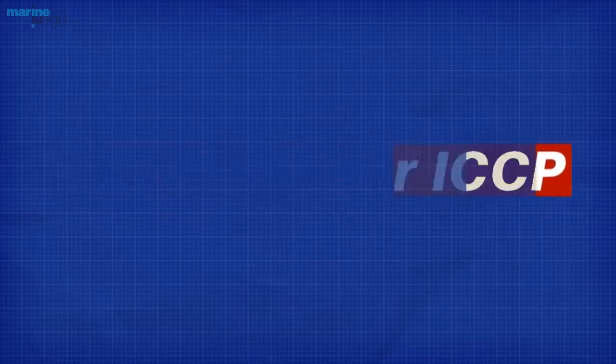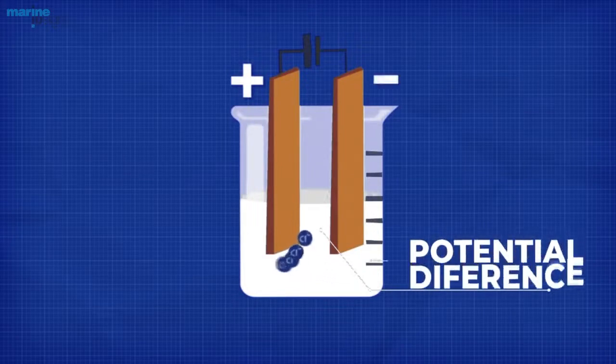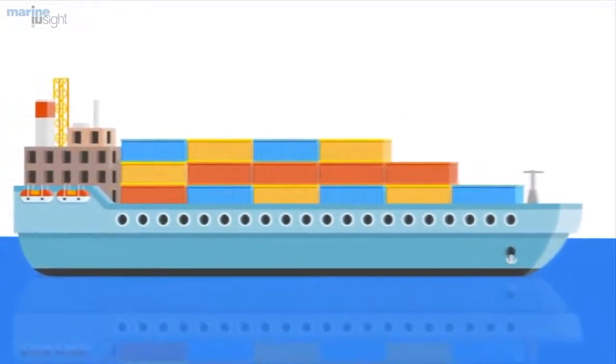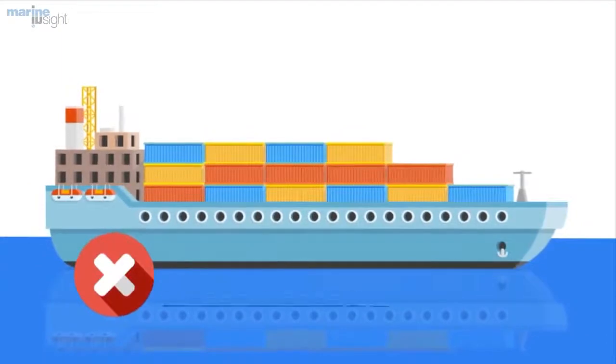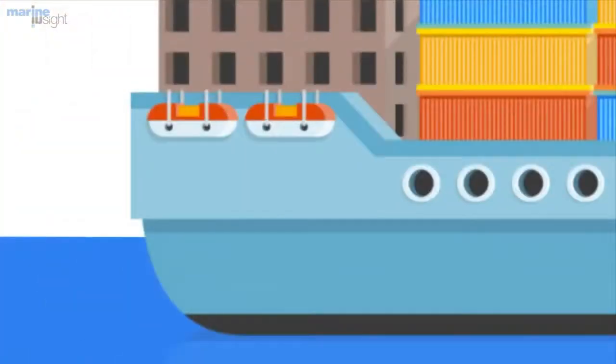We now know from the galvanic cell and the sacrificial anodes that a potential difference between two electrodes is required for corrosion current to occur. This corrosion current dissolves the anode in the electrolyte. But in the absence of a potential difference within the ship's hull, the corrosion current will be at minimum. This is what the ICCP, or the impressed current cathodic protection, does.